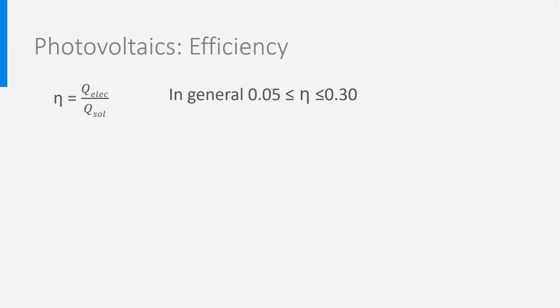So, on one side, the photons in the solar radiation have a much higher energy than the energy needed by the electrons to jump to the P side. This excess energy is lost as heat. That is around 30% of the incoming solar energy. On the other side of the spectrum, the photons from the infrared have too little energy to boost the electrons. Also, this energy is lost.